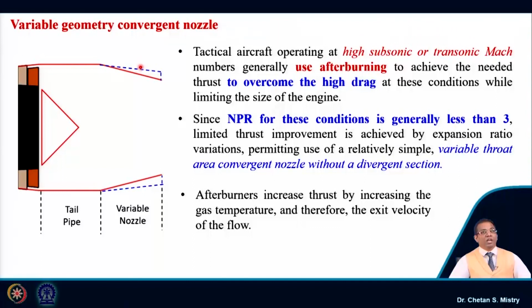If I use the same nozzle, the maximum possible mass flow rate passing through the exit of my nozzle is restricted by M equal to 1. That is called the thermal choking condition. So, once my nozzle is choked, no further increase of mass flow rate is possible, and under that condition, in order to have higher exit velocity, we need to go with a variable area nozzle. Okay.